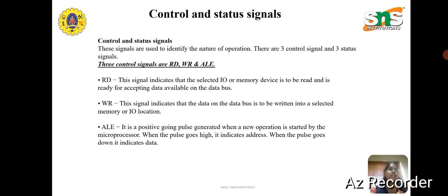And ALE is a positive going pulse generated when a new operation is started by the microprocessor. When the pulse goes high, it indicates address. When the pulse goes low, it indicates the data.